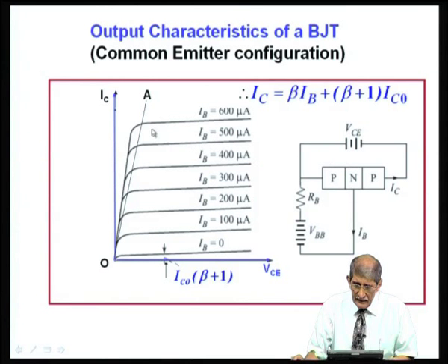So, when it is reverse biased, collector current will be proportional to the emitter current and therefore, proportional to base current by this relationship beta times IB. Beta is large. If it is microampere, you will have milliampere current there. Now, okay, if this is 0.6 volts, I said this will be 0 here, because 0.6 has gone into this.